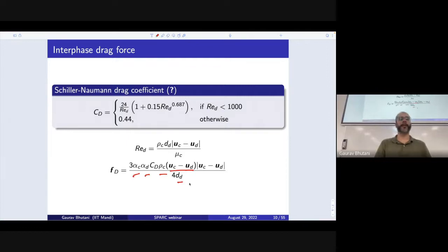And that's very important; in some cases, that can have a significant effect. And that is the reason we need a population balance equation, to get information on the size of those bubbles as a function of space and time. So simplistically, if one does not want to model the polydispersity in the system, but still wants to model the flow dynamics, they end up taking a monodispersed system. They assume that this particle size d is constant. But in some cases, variation in the particle size can have a significant effect on drag force dynamics, and that whole prediction changes in terms of flow.